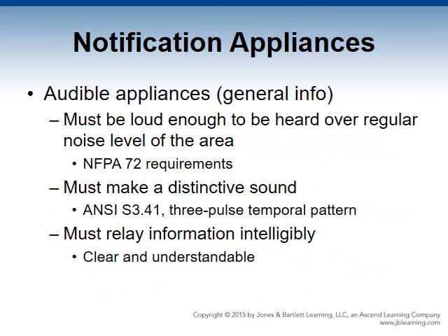Audible appliances and audible devices must be loud enough to be heard above the normal noise level of the area. NFPA 72 establishes audible sound level requirements for occupied areas. It regulates the duration in decibels for various scenarios. Audible devices must also make a distinctive sound to avoid confusion with other signals, including those generated by the fire alarm system.